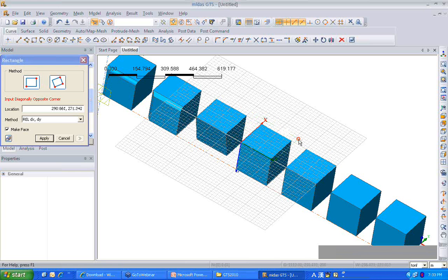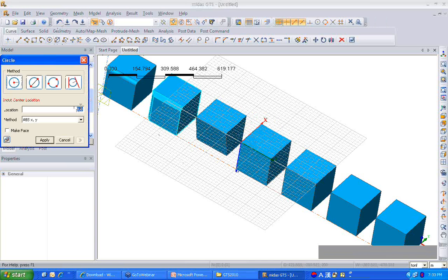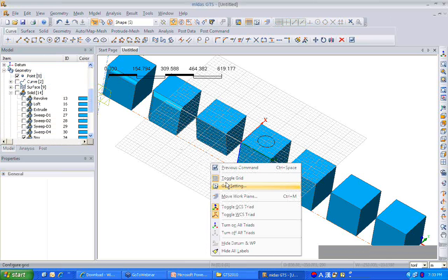Or you can do one thing apart from using this thing. Let's create a small circle on this thing, and I will extrude the whole circle. I will just cut the whole tunnel through the solid using prism function. So let's have a circular profile for your prism, and here we are done.